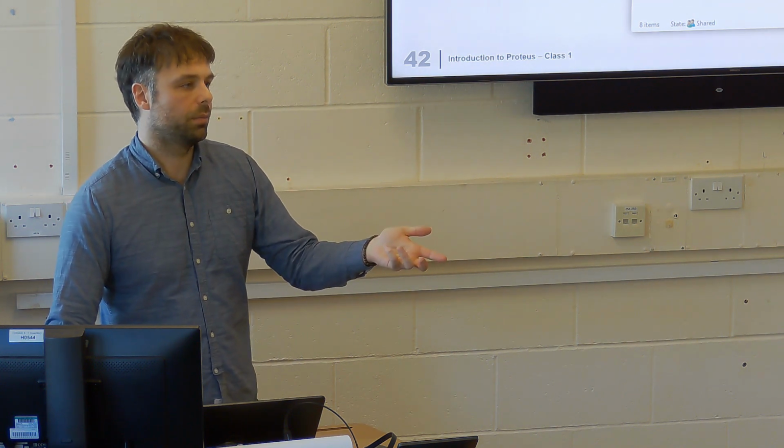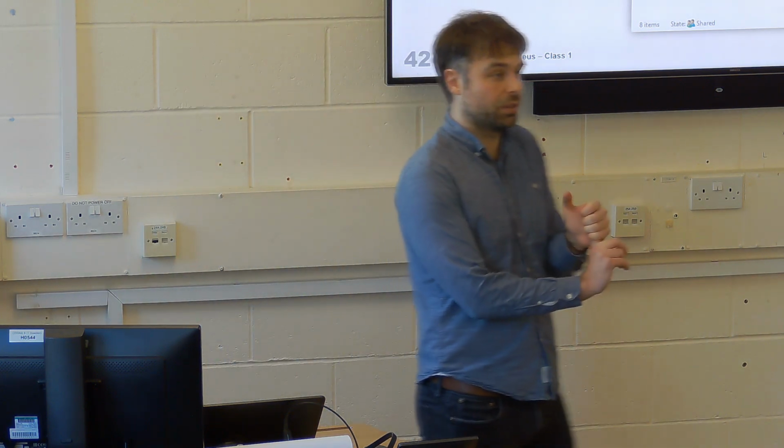Transformers? Not transformers, but I will go on to the library that will contain that one. Diodes? No. So electromagnetic is essentially anything that can move with electromagnetism. So motors would go in there, obviously your relays would go in there, solenoids, that kind of thing. The next one's a magnetic library. Now what would go in the magnetic library? That would be your inductors, and that would be your transformers. Anything that is mainly inductive, you'd stick in the magnetic library.